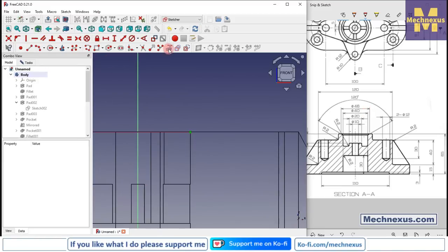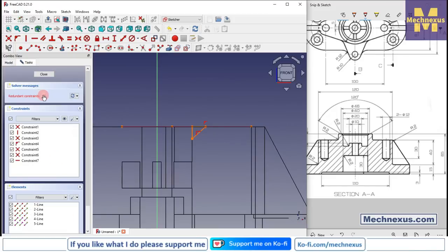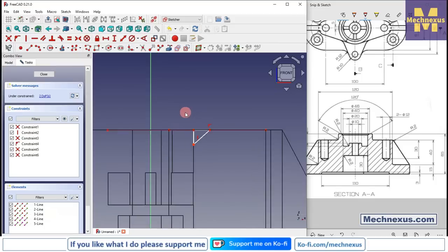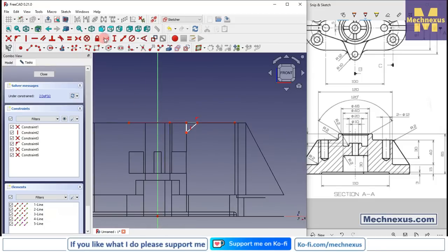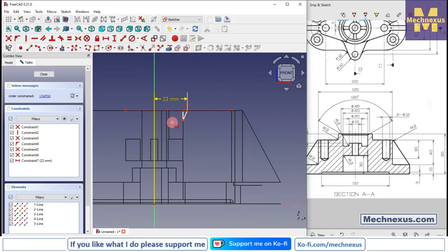So first thing which we will do is to select line tool and click on project geometry, select line and create a triangular profile, and we will go to the sketch and remove this conflict, click on delete, and now here we will select horizontal dimension, select this point and this point, and add a value of 23 because it is a 46, and we will provide the angle.